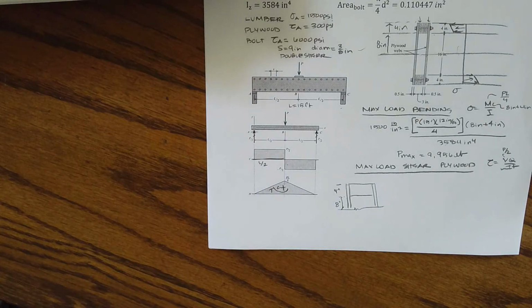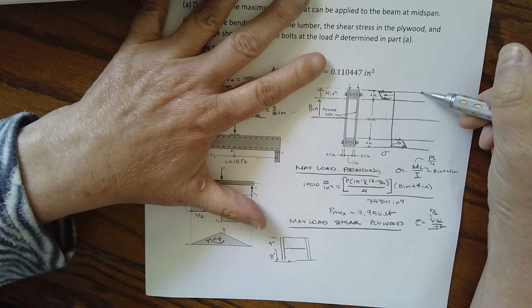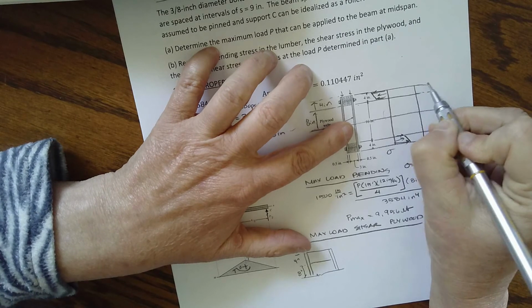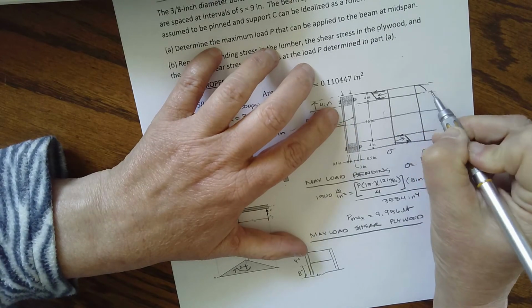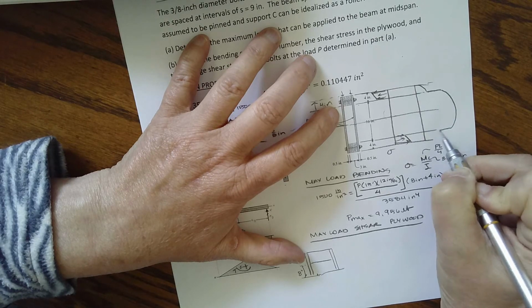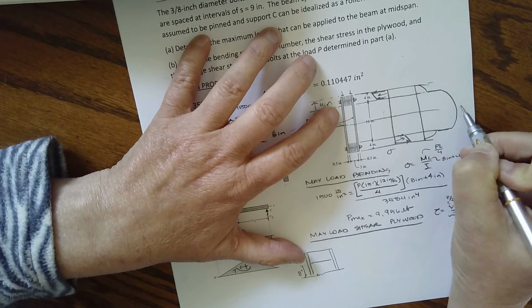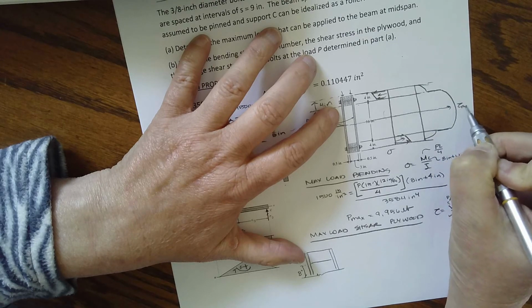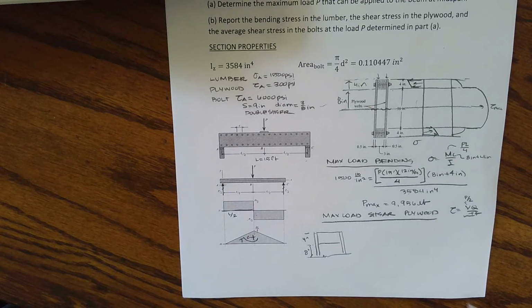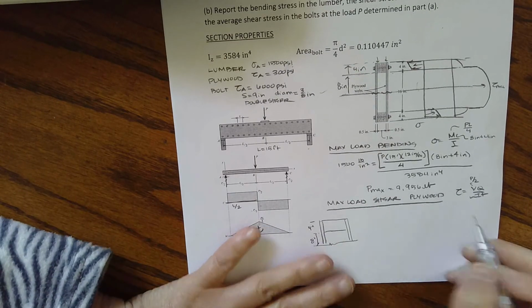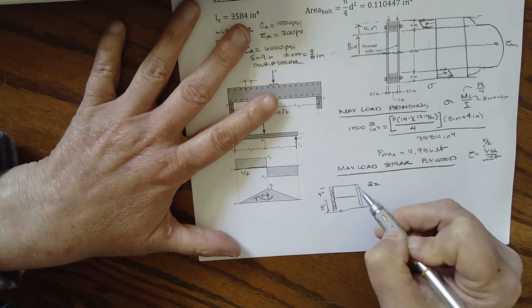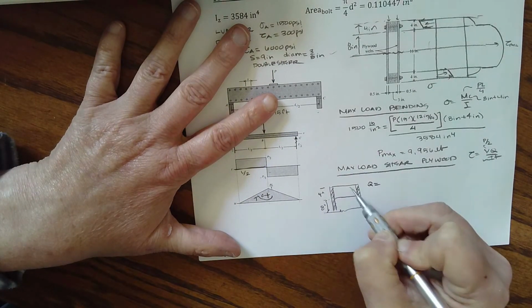And I have to understand that maximum shear stress occurs at the centroid usually. Okay, so we're going to be coming down. We have a change in thickness. We have that jump, kind of come back around, change in thickness. That doesn't look symmetric, but we know that the maximum is going to occur right here with these plywood walls wanting to shear. So when I'm looking at this, my Q value, I have this area and this area plus this area.